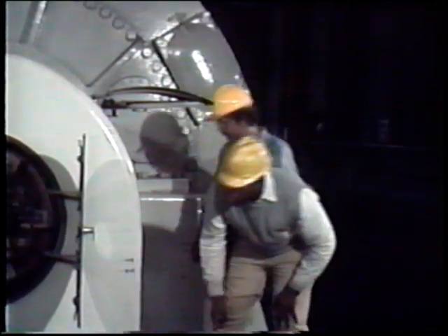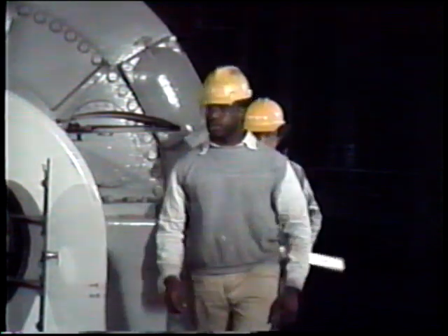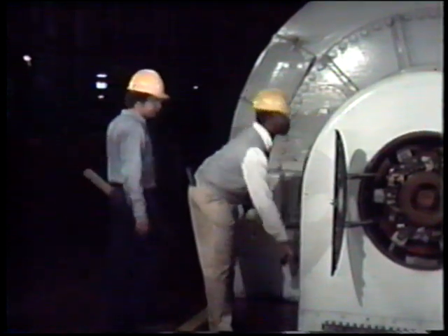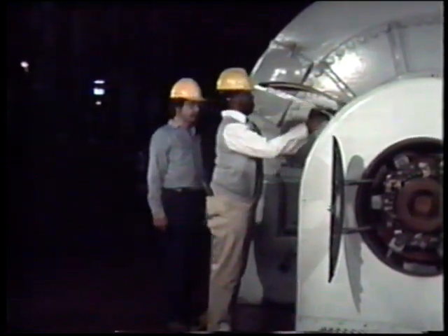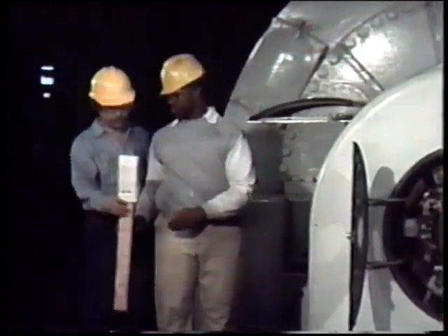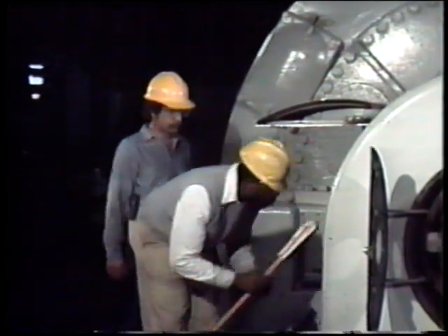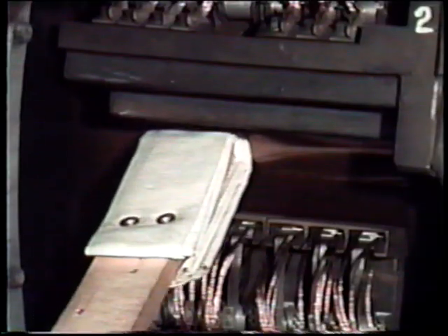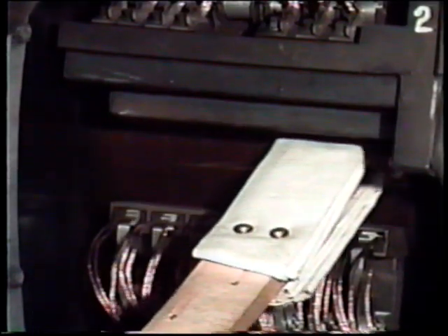Next, the electrician cleans the commutator to remove carbon dust that's accumulated there. As the brushes wear down, carbon dust is produced. Now, carbon is a conductor, and if carbon dust builds up, it will eventually short the commutator segments together. Carbon dust could also cause grounds. He uses a canvas wiper because canvas is sturdy enough to be held against the commutator without tearing.